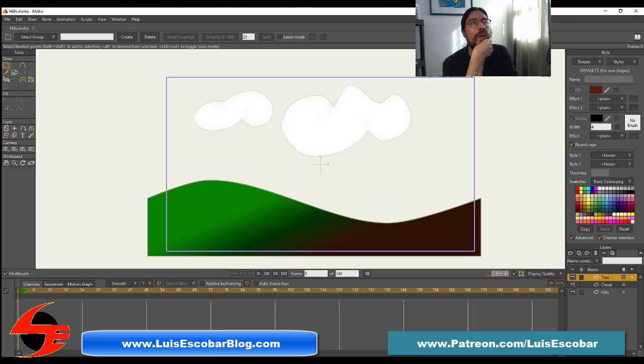Third, the transform points tool lets you pick individual points by clicking on them. If you want to get rid of a point but it's too far back to use undo, select it with the transform point tool and press the backspace or delete key on the keyboard. Feel free to be creative with the tree trunk. You don't really need to stick to the sample below.